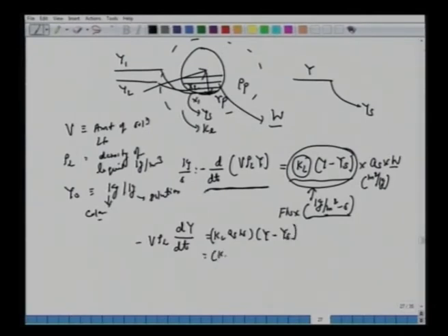YS is the surface phase concentration, or concentration of solution near this solid surface. We said that because of our assumptions, everything is controlled by this interface mass transfer, and the kinetics are faster here, whether it's diffusion kinetics or pore diffusion kinetics. YS is in equilibrium with this X solid phase concentration.